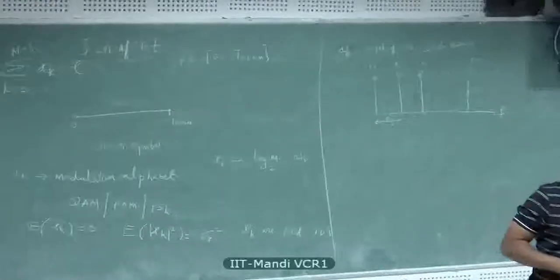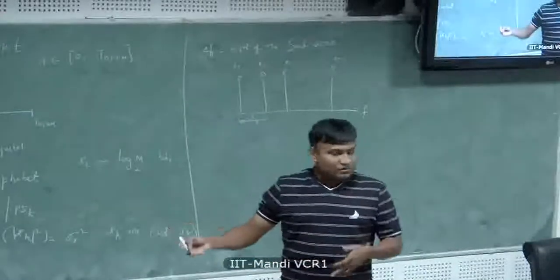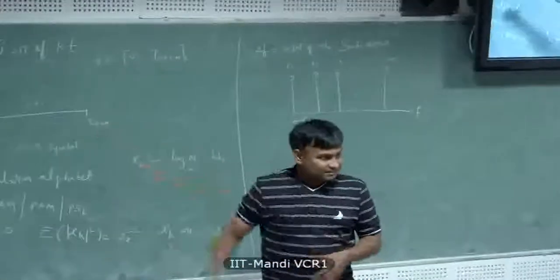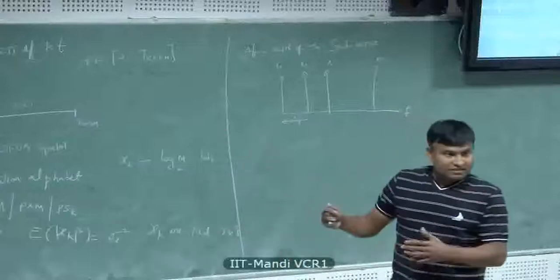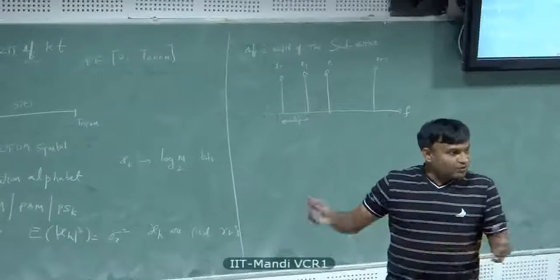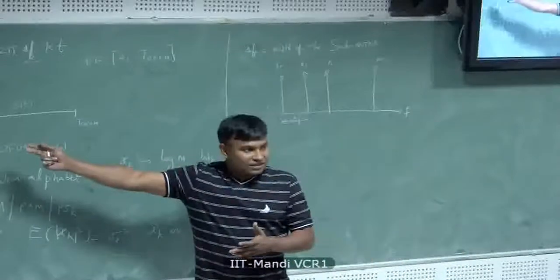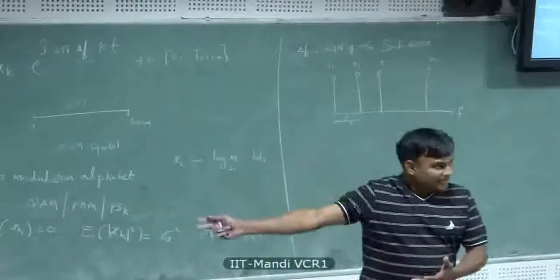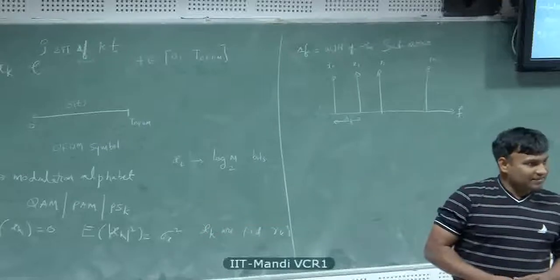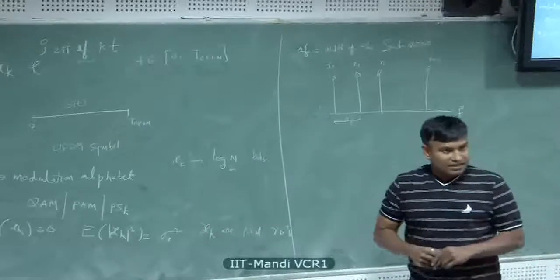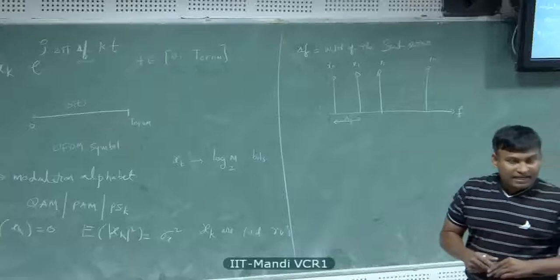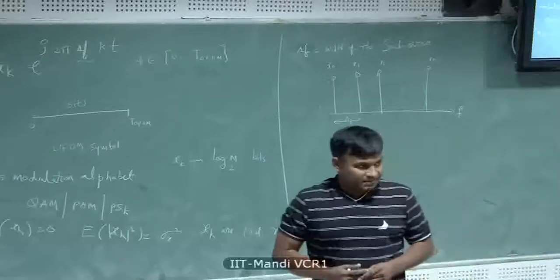That is the beauty of multi-carrier system or OFDM, because there is a lot of flexibility in choosing how you transmit, because you can simply null out some tones and you can control the bandwidth occupancy. Okay? And in fact, you can control the bandwidth in a very flexible manner. Of course, it doesn't come for free. When you null out some tones, you reduce the bandwidth, but you also lose the data rate because you're not transmitting those symbols. Okay? You can't change the basic trade-off between data rate and occupied bandwidth.